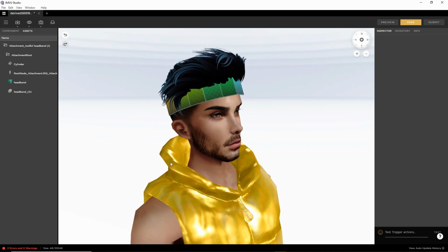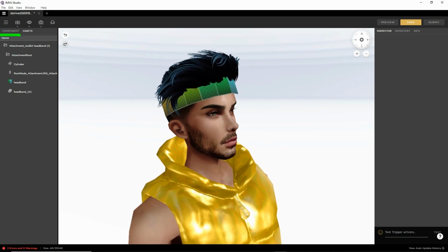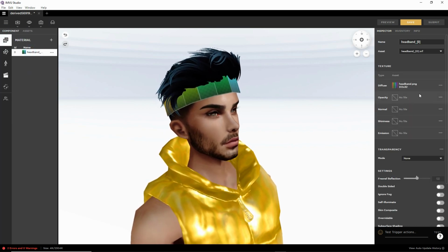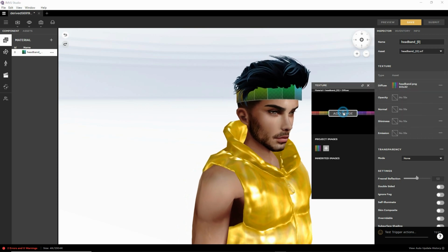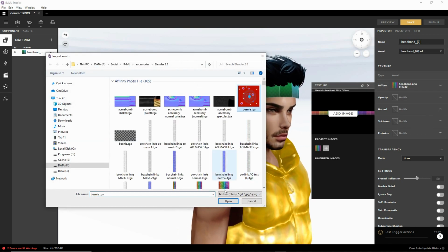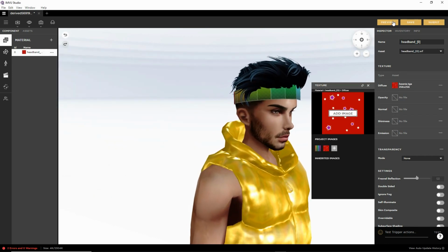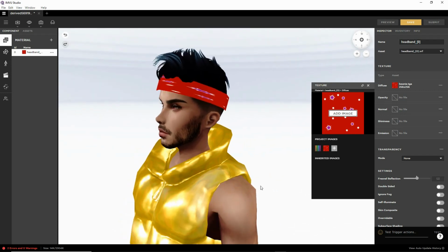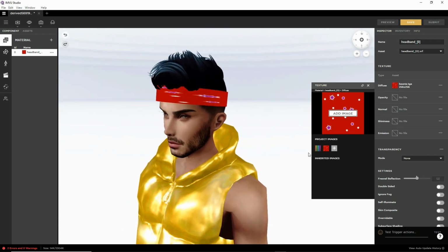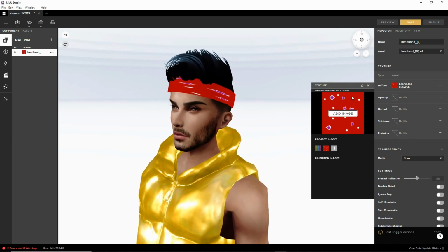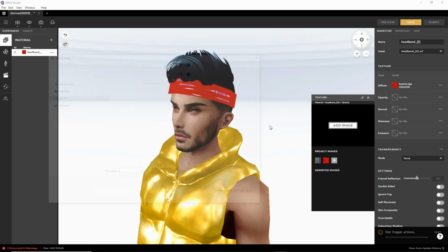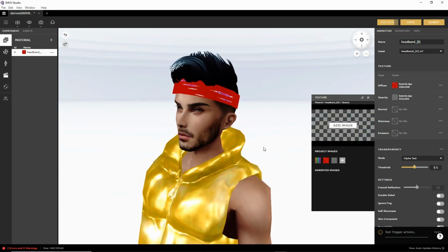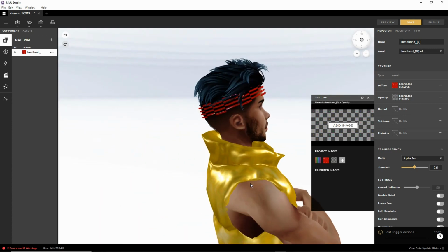And of course, all we need to do next is go into component and edit the material that's assigned, so we can change the image if we wanted. Let's just use that one for now. Preview. It's a bit smushed because of the scale difference, so this is a square image as opposed to the very thin lozenge. We can assign opacity. Let's just use any old image that we've got. But this would be your proper opacity map.